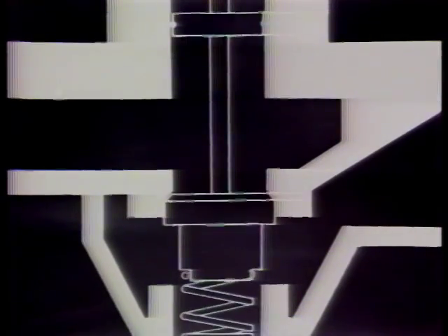The space behind the piston also provides for a dashpot effect, which has a tendency to smooth out valve movement. The second design also uses a piston the same size as the seat, but this time it is attached to the upstream side of the valve by a stem. The upstream pressure pushes on both the valve face and the piston equally, balancing the pressure across the valve.